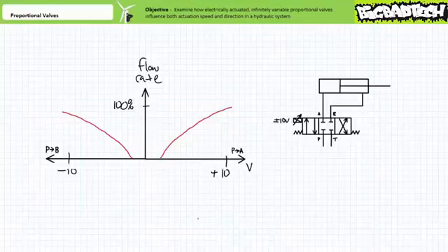Additionally, these curves are constructed assuming a constant pressure drop across the valve. Proportional valves, despite their superpowers and associated expense, largely behave as would a regular flow control valve in that variations in pressure upstream or load-induced variations of pressure downstream would also serve to change the observed flow rate through the valve. Related to this phenomenon, the super observant and fastidious among you will note different flow rates for the straight-through and cross-connect positions given the same applied voltage.